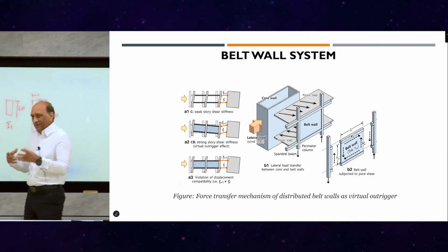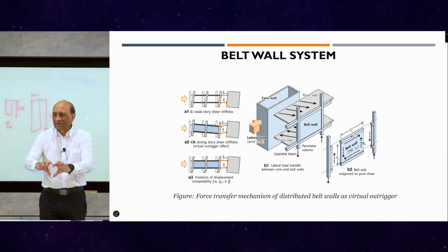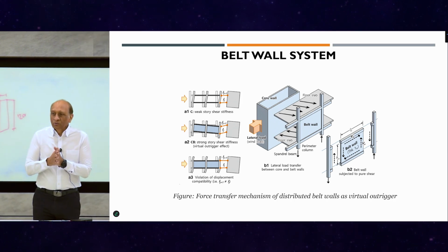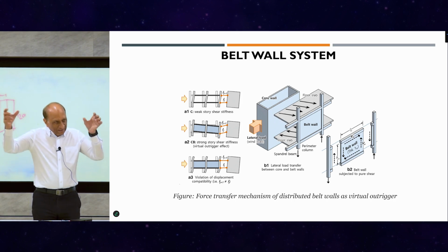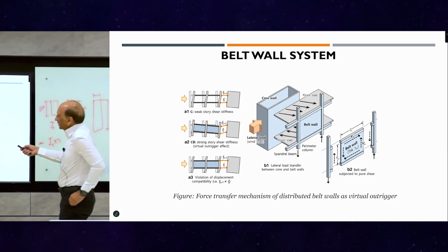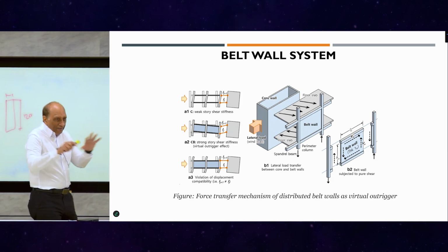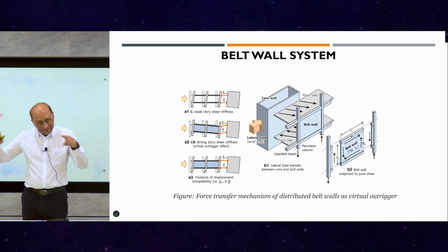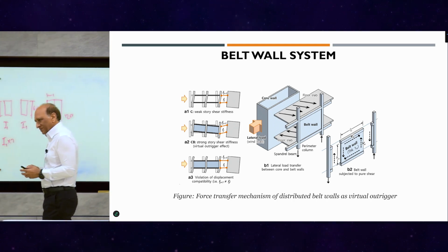Sometimes in some buildings you will see that they bring the columns up to this one, and then they just remove the columns and transfer them to mega columns, which we will talk about. Another concept, completely change the system to not have the columns in the middle participate at all, right? Yeah. So just have a belt resting on the outer four columns, remove everything else. So make it very, very simple. So that's the whole concept of the belt wall system. Belt, wall, outrigger, virtual, real, everything is combined. So people can use all kinds of things now. You can make trusses, you can make outer trusses, you can make walls, you can put VRB, you have the freedom to do all kinds of combinations.